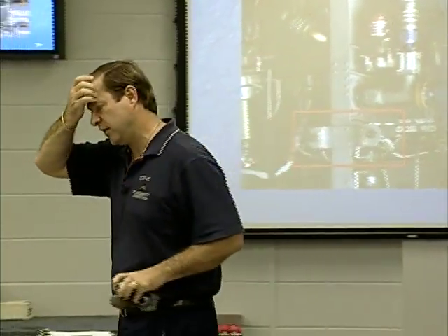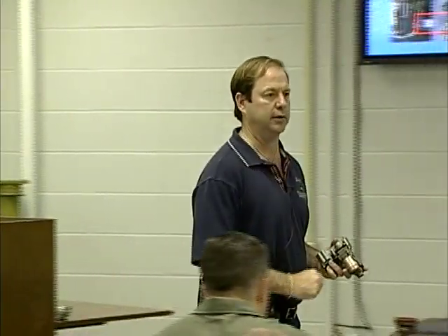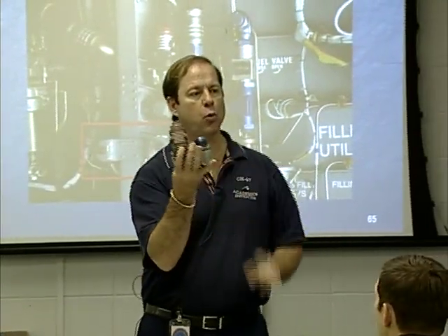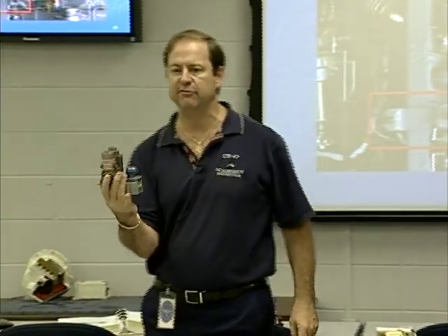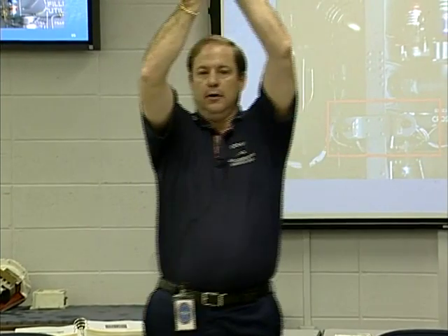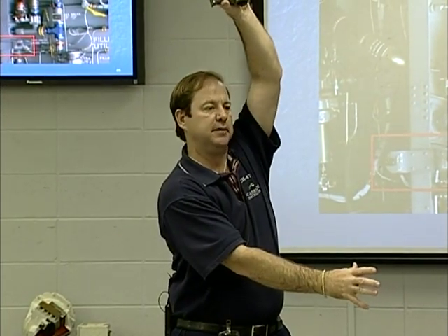Now, what's the problem with that? A lot of people question, why do I need 2 of them? Why don't I just have one for the crossover line? Where would I put one valve that's going to allow me to trap fuel in that crossover line? If I put it in the center, then the fuel's going to drain back out and that crossover line's going to be empty.